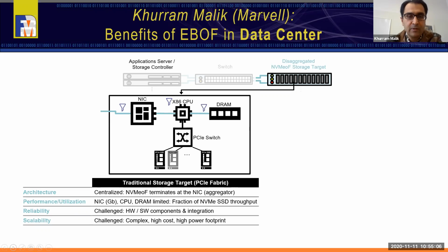That dictates whether we need a PCIe switch in between for fanning it out, and how many DDR are required based on the number of channels it supports. On top of that, we need to decide how many smart NICs can go in a 2U enclosure. So when we think about this architecture, it also starts with all the limitations that come with the CPUs, with the DDR bandwidth, and with the NIC connectivity.